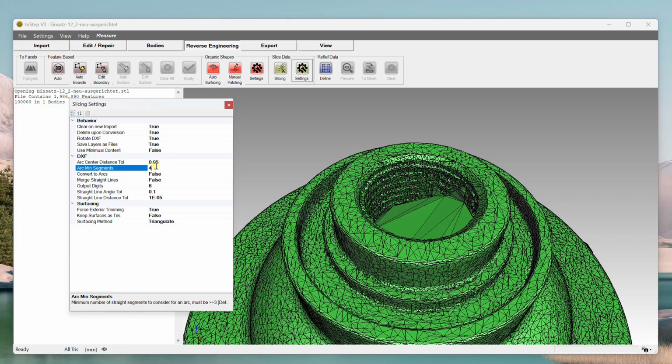Generally, you can turn that on if you want to use that. That's fine. Generally, I recommend you keep this off. That way the application will just output straight segments, and then you can use your CAD application as a way to create a better fitting arc through that. The reason for this has to do with parameters that you may want to carry over, or the application may find things that you just inherently don't think should be an arc. It may look like one, but it's actually not. It may be part of a chamfer or something like that.